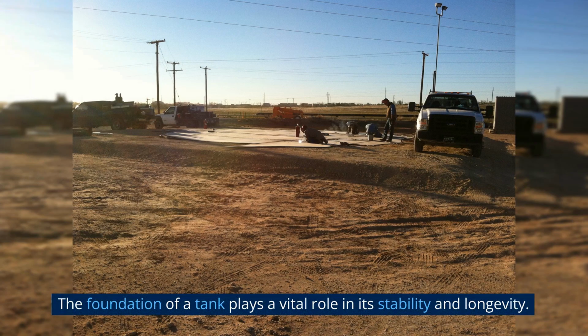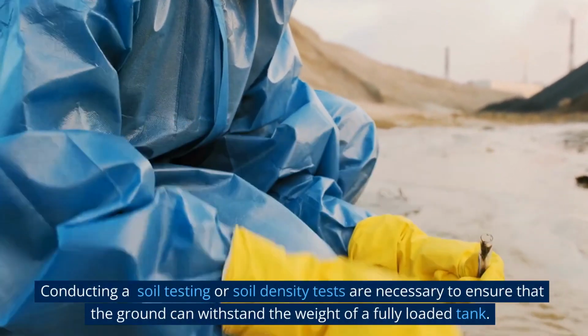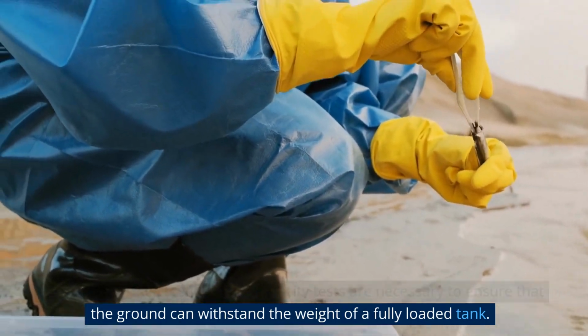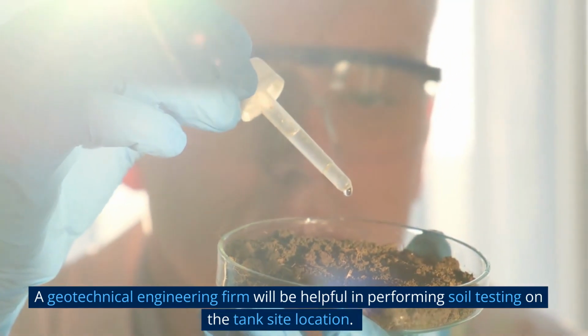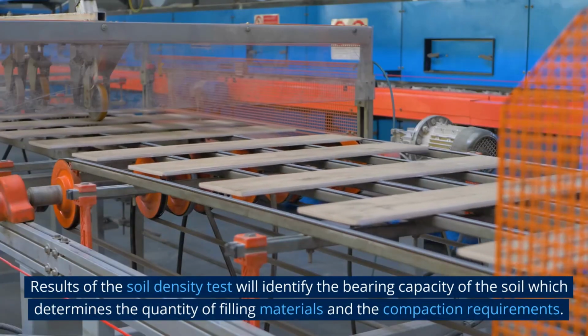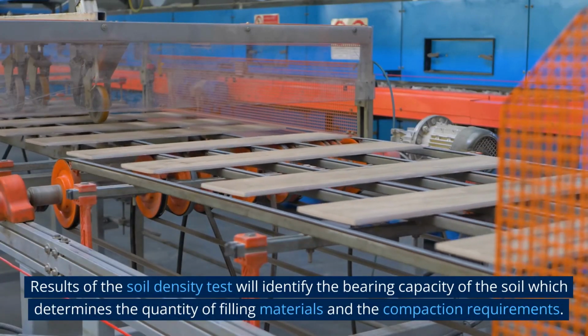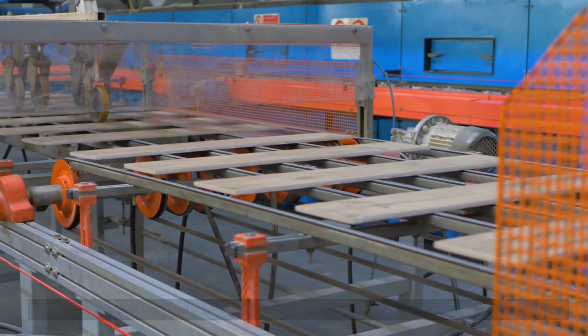The foundation of a tank plays a vital role in its stability and longevity. Conducting soil testing or soil density tests is necessary to ensure that the ground can withstand the weight of a fully loaded tank. A geotechnical engineering firm will be helpful in performing soil testing on the tank site location. Results of the soil density test will identify the bearing capacity of the soil, which determines the quantity of filling materials and the compaction requirements.